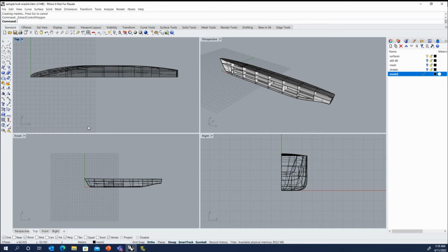If you want to do that with the script, what you would have to do is create a cutting plane and then split the lines, similar to what we did with the hull curves, where we split the hull curves deck by deck. You would basically take all the curves that we created along the length and split them where we wanted to change the spacing, and you'd run the script twice. Once for the inner curves, once for the outer curves, and with different spacings.